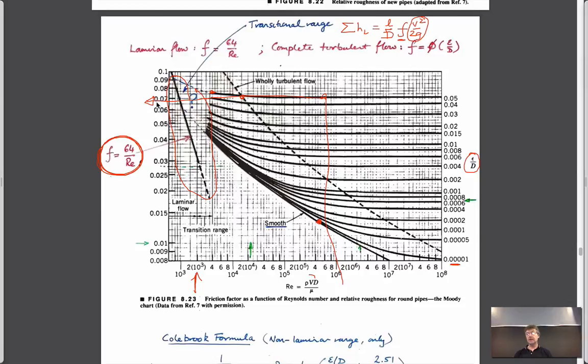We just have to understand where this comes from. So again, dimensional analysis, incredibly powerful technique. Only for very simple geometries can we get analytical solutions, which are these laminar flows in very specific pipe cross sections. If we want to deal with real flows, then we actually have to do experiments to figure out what the dependencies are. But dimensional analysis can guide us in that, to give us the correct kinds of expressions and to guide the experiments we do.